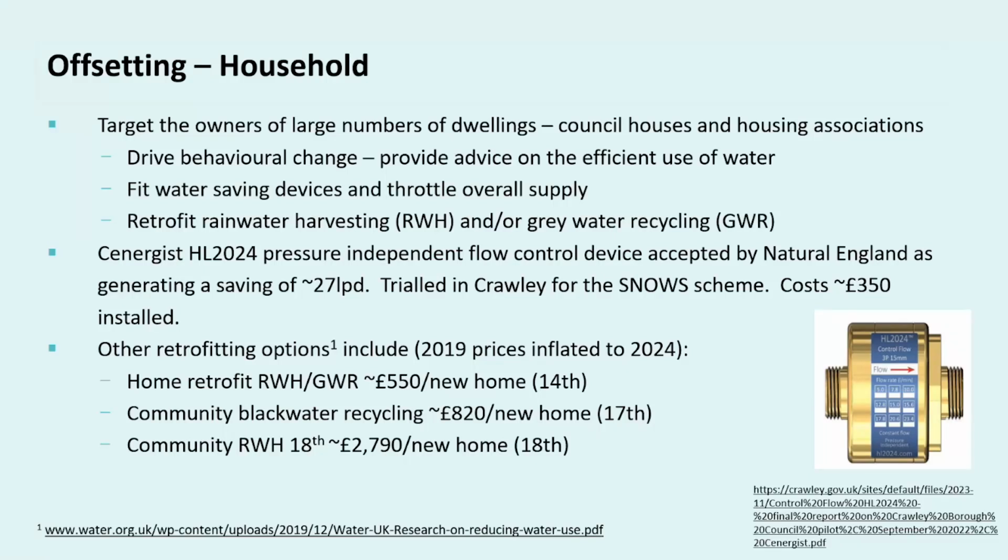As the devices are plumbed in to the cold water feed, they can't be readily removed. You're not meant to tamper with the water company side of the supply pipe. And so Natural England, I think, and the Environment Agency prefer this approach to the installation of tap aerators and shower inserts, etc., because it can't be easily removed. Also, because the water neutrality issue in Sussex North relates to habitat sites, a very high level of certainty of mitigation must be demonstrated through the habitats regulations assessment. It's a very high bar to achieve.